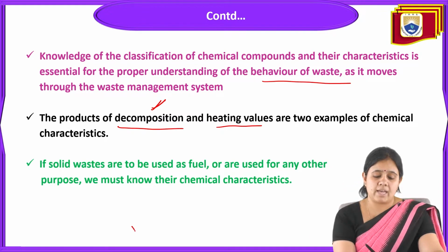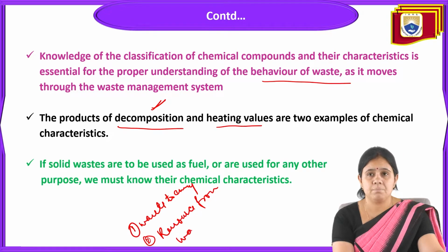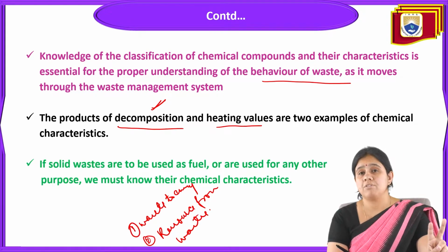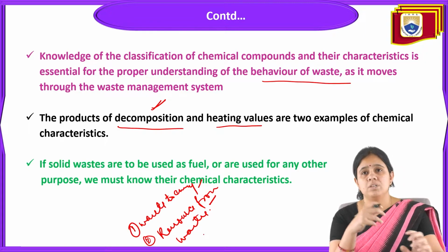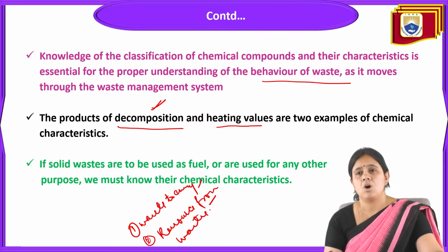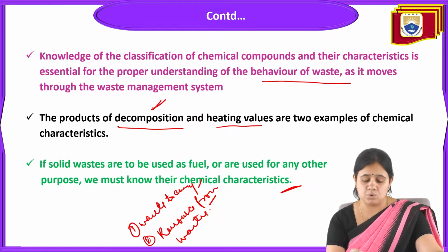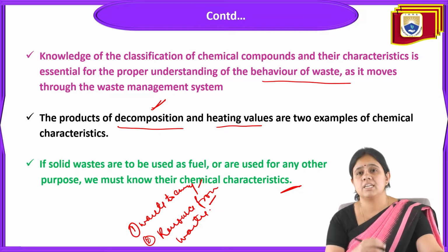First is waste to energy, and second is resource from waste. These are now very burning topics. So for these two perspectives, you have to know the decomposition and heating value of that particular waste. If solid waste is used as fuel, or for any other purpose, we must know its chemical characteristics. Only then can you study its decomposition process and its heating value.